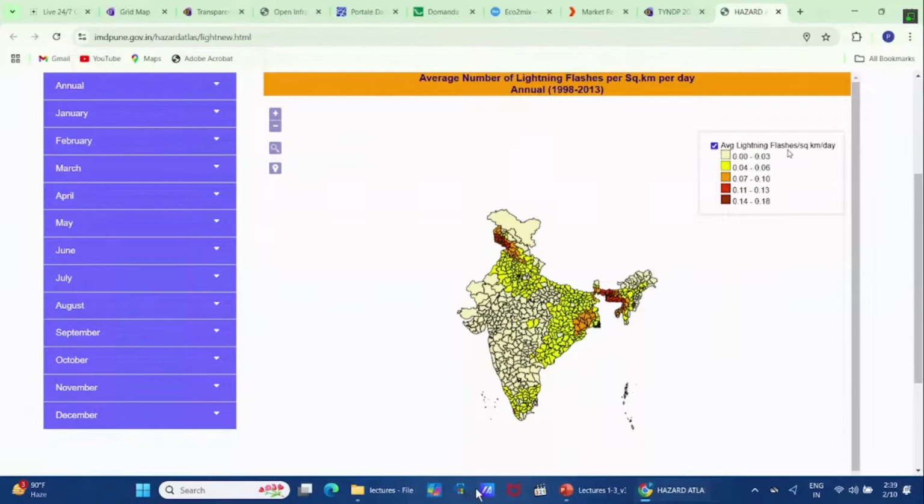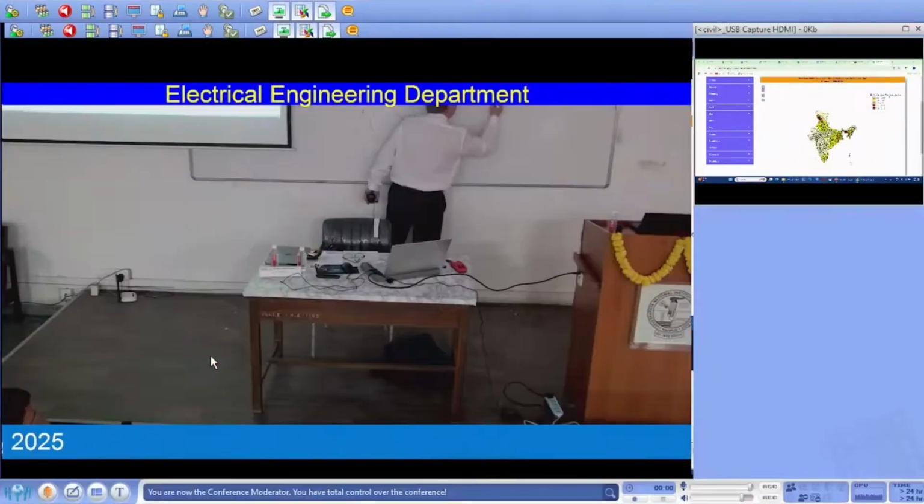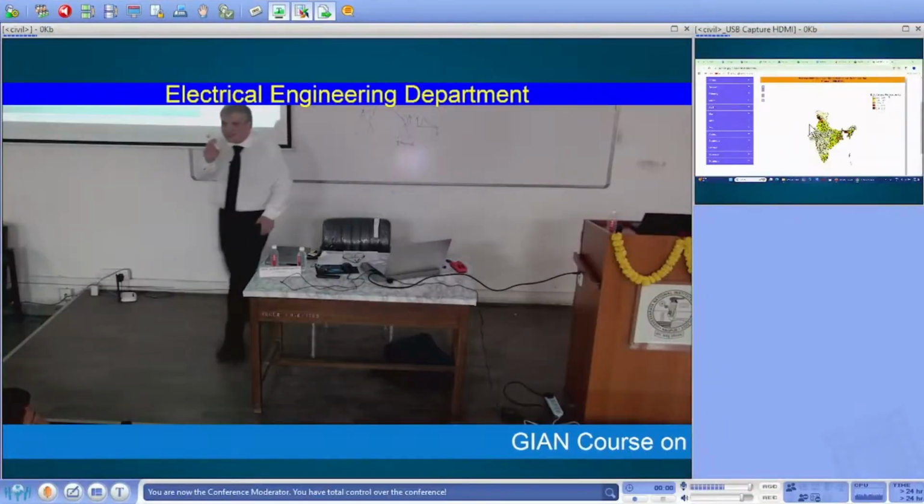But since the path is already ionized after the first stroke, depending on the conditions, you may also have after some time that the charge from the cloud follows practically the same path. It can be, for example, from that way to another structure nearby, no? And creates therefore another return stroke. So the return stroke is indeed the event that we are interested in.